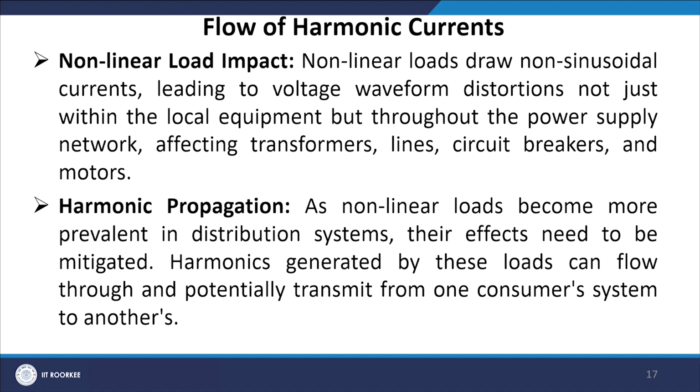Harmonics generated by these loads can flow through and potentially transmit from one consumer system to another. Harmonic frequencies are quantified as a percentage of the fundamental frequency component. Different situations affected by harmonics may require diverse characterization methods. The crest factor is one metric that measures a type of distortion.